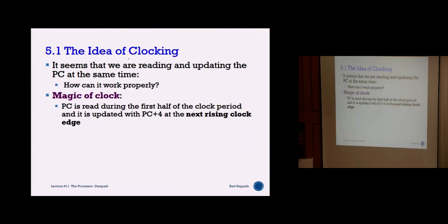In all our systems, we talk about clocks as the key to running a system. Why? Because everything is based on a clock, especially when you're talking about a processor. When you say this processor is running on a 20 megahertz clock, or a 1 gigahertz clock or whatever, that is the overall system clock. That tells us how fast your processor is executing. But of course, if you talk about a complex system, you may have different clocks for different subsystems. So even though you say your main processor is maybe running at 1 gigahertz, that is only your main processor.